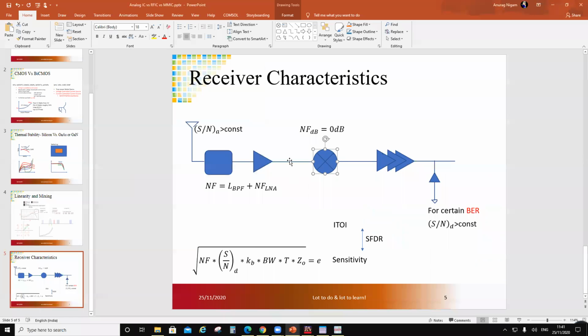Now if I was to put a gain of 20 here, then it will be 0 minus 20. So this can go, and then plus this loss. So 0 minus 20, it will be minus 20. Minus 20 plus, let's say, a dB loss in this, minus 19. So in this case, this would saturate at minus 19. Correct?